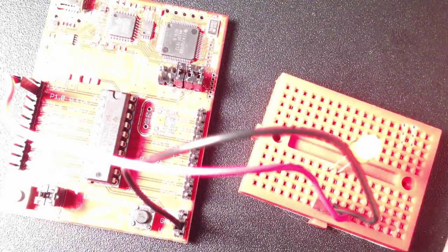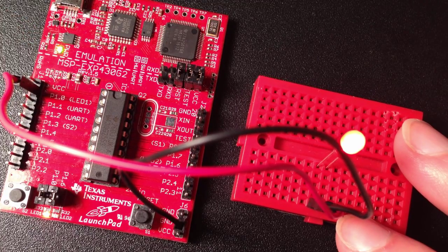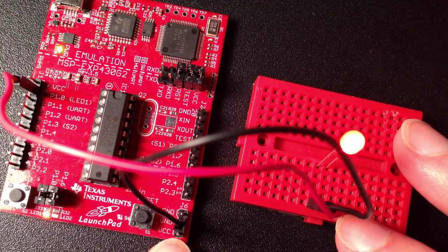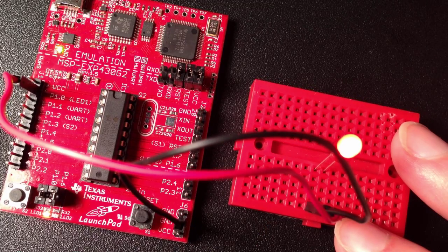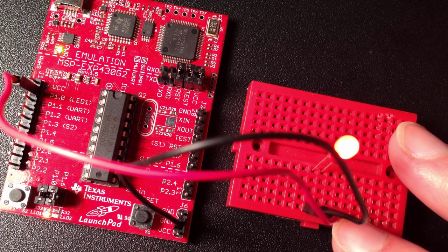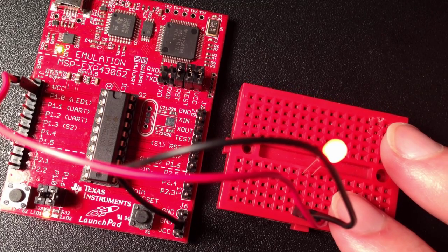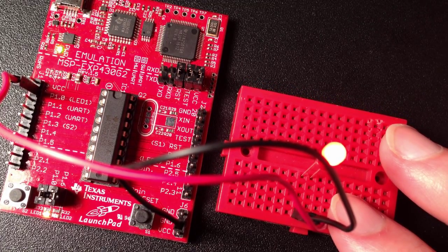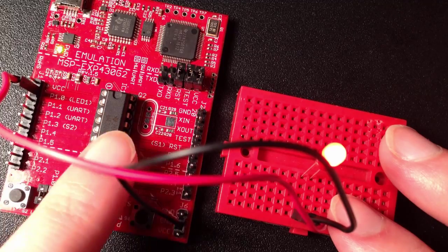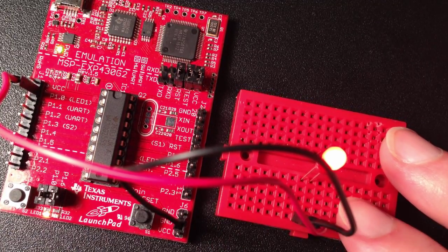Now it's worth noting that you could also connect this wire to the VCC pin, which is just straight power. There's no program to affect whether or not voltage is going through that or not. This isn't recommended. You can blow LEDs by doing this. So if you need to power anything, the best way to do it is to set up a small program to turn the pins on that you need, and then wire them to the board correctly.